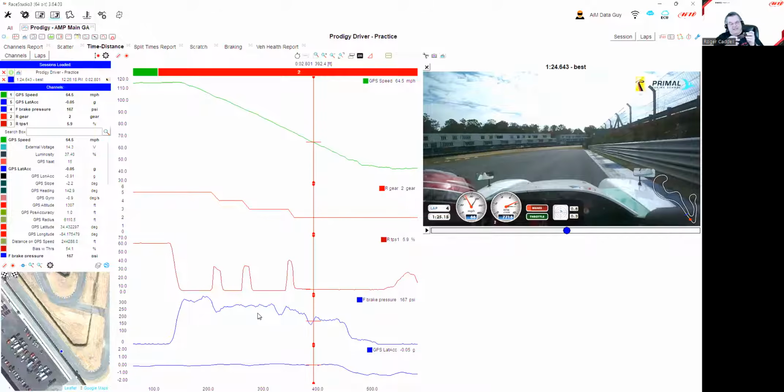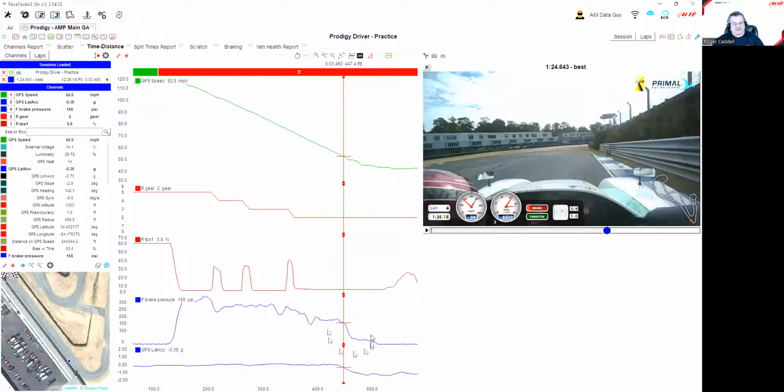Then you start this trail braking effect. You start turning in, and now you're still on the brakes, and you've got it loaded. Let's say it's a left-hand corner: the right front corner is getting an extraordinary amount of load, all because of what your hands and feet are doing. If you're not being consistent, the loads go up and down on that tire. We will see drivers lift off the brakes right when they go to turn in, and they'll just dump the brake pressure. You see a little bit of that here, right here. The driver dumps brake pressure right when the driver is turning in.